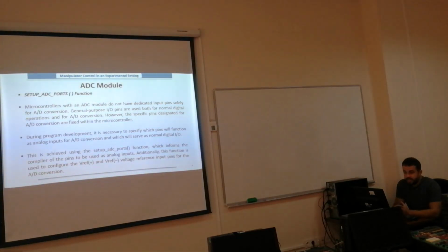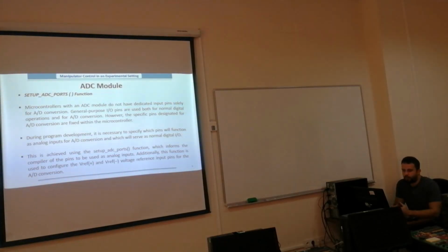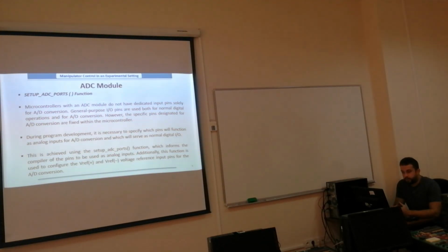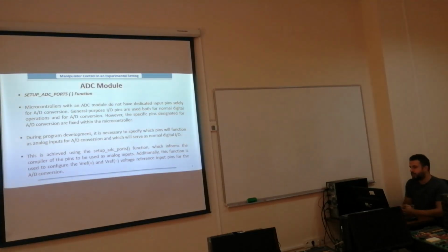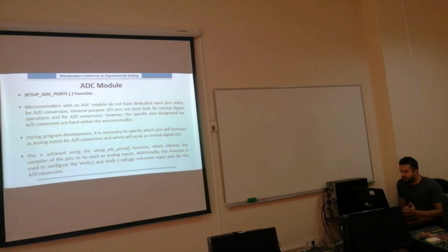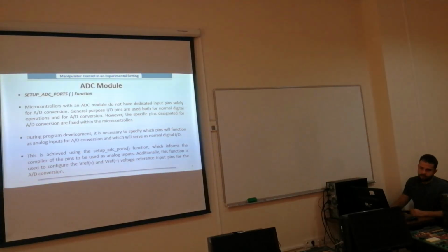Therefore, this is achieved using the setup ADC ports function, which informs the compiler of the pins to be used as analog inputs. Additionally, this function is used to configure the positive and negative reference voltage input pins for the analog digital conversion. In this study, positive 5 volts and 0 volts will be used as the positive and negative references respectively.